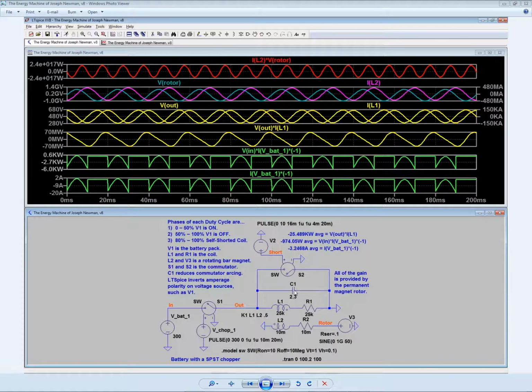It was difficult enough, and I had to fine-tune this capacitor just right. It became a very narrow window. Not too high, not too low, lest I lose this predominantly negative amperage. And I had to also achieve a voltage on the coil of close to 667 volts, and I achieved a high of 680 and a low of 280.